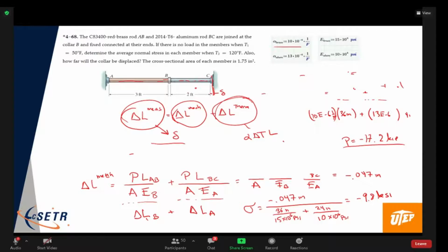It freely expands by alpha delta T, and then you have to squash it down, not quite that alpha delta T, because it was allowed to freely expand by delta, and that's what gives you the stresses in the actual elements themselves. Those are basically the two types of problems you have. Like I said, there's no shear equivalent to thermal expansion unless you have some funky, unbalanced composites or something like that. But again, it's a pretty important source of stress.